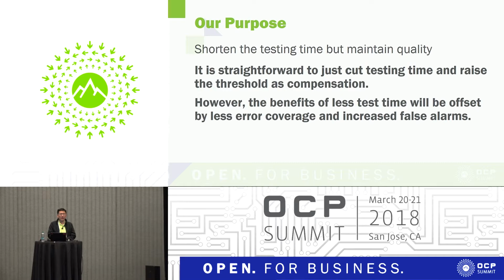You think, I don't want to spend a whole 72 hours, or the whole 3 days, to test the DRAM. Can we just test in only 1 or 2 days? Okay, but at the same time, you have to change your threshold, maybe to a more rigid threshold, to filter out the DRAM module. However, the benefit of less test time will be offset by less error coverage.